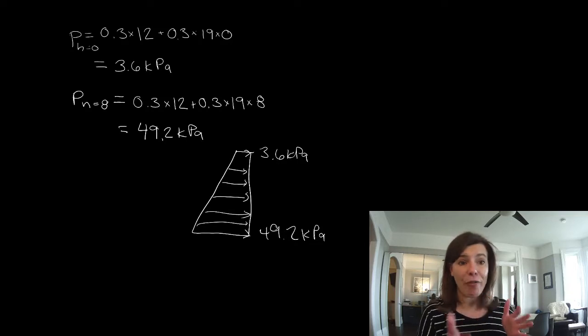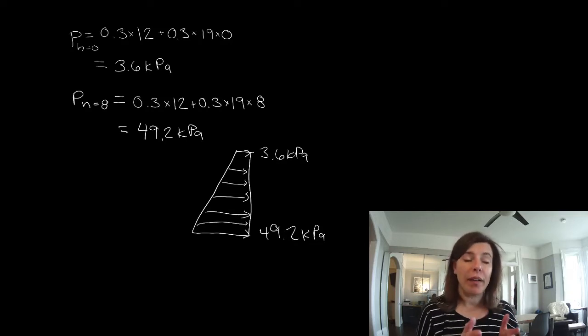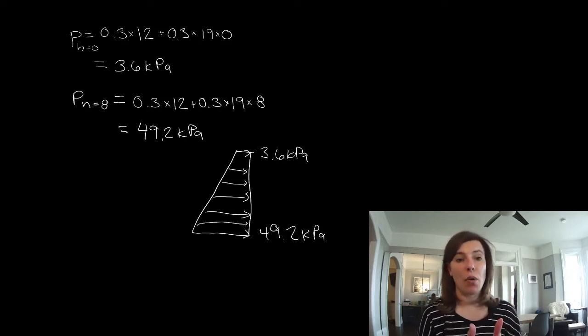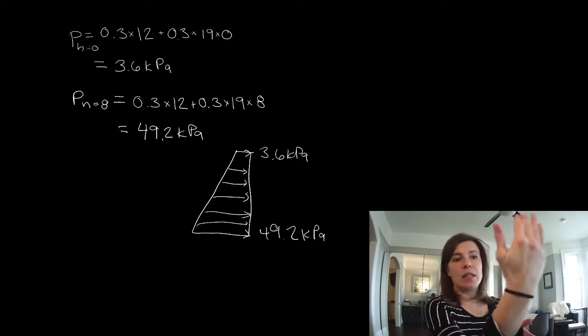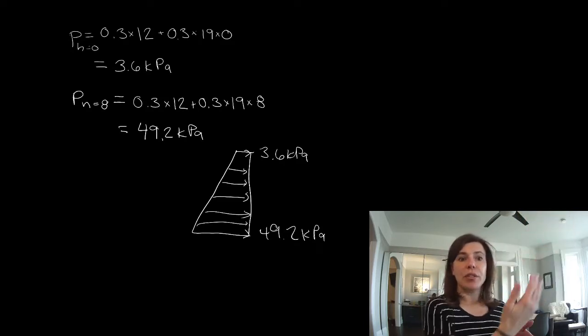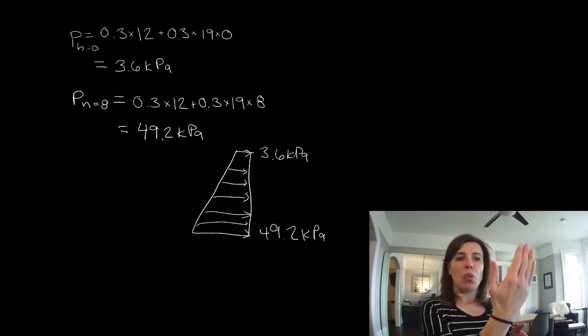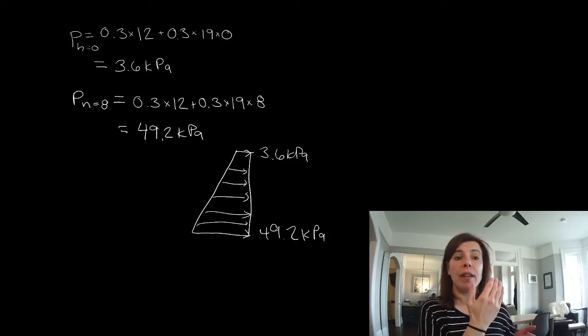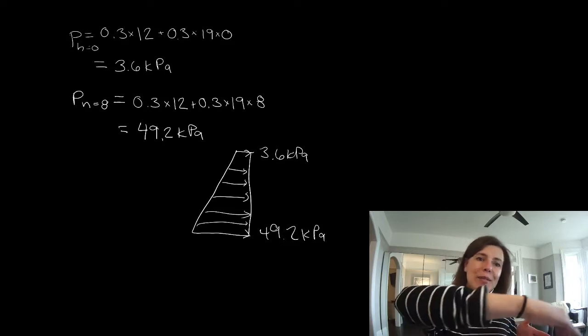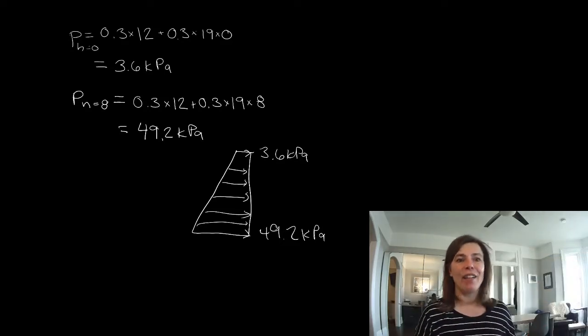We have it everywhere, and you throw a little rebar in and you can have the same strength everywhere. Versus our steel construction, for example, where locally, where we would have beams, or in this case, rakers, to make a foundation wall, we would have very good ability to resist the soil. But in between whatever we had there would be somewhat weak, like our metal deck, if we were talking about something on plan.